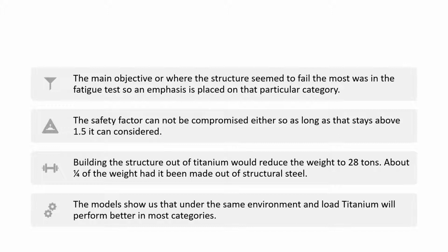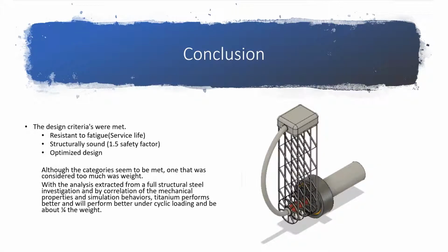The model shows under the same environment and load that titanium will perform better in most categories. With all this said, I guess the next step would be to test on titanium, get full S-N curves, and test that out. As a conclusion, the design criteria were met. It was resistant to fatigue, service life, structurally sound, with a 1.5 safety factor, and the designs were optimized to handle the most loads while not using as much material as possible.